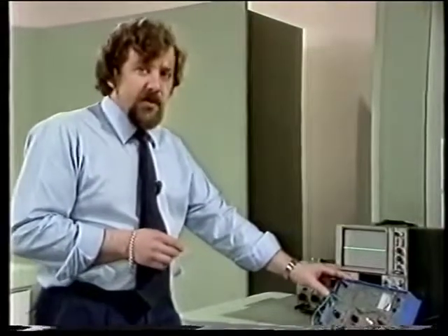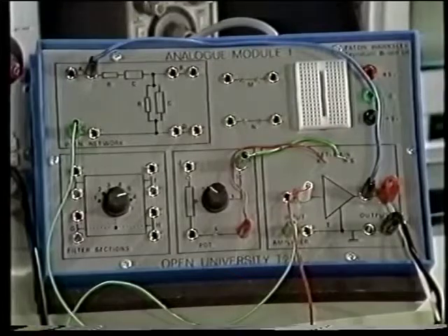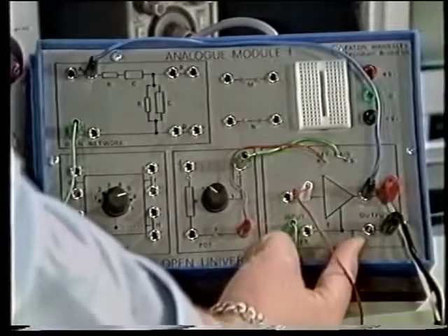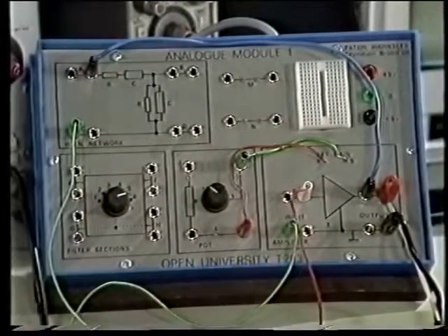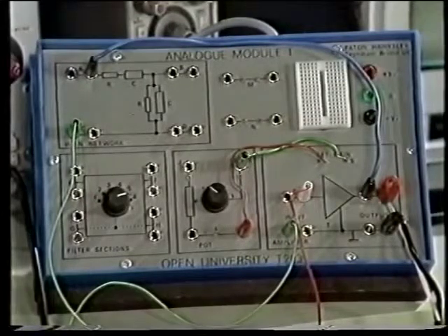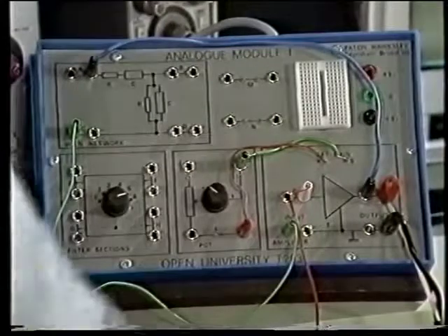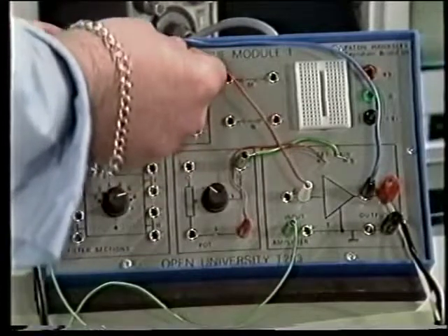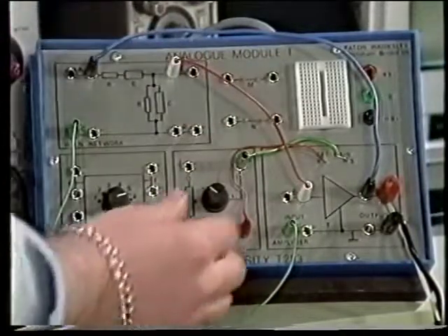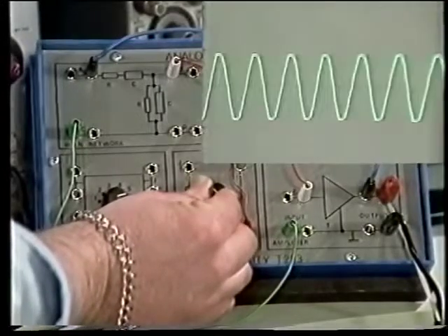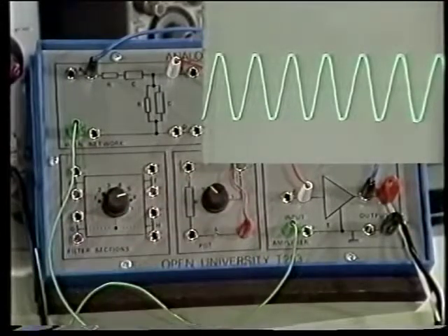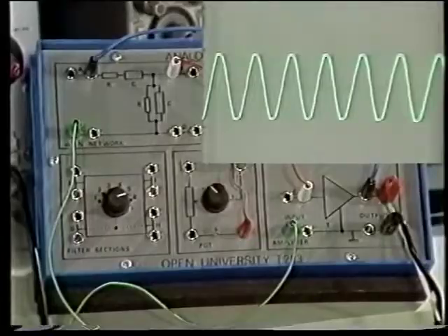As in the home experiment, I'm actually using one of the modules. I've nearly finished setting it up. This is the amplifier. Its output goes to the Wien network, and I can close the feedback loop going from the output of the amplifier to the input of the network. And if I get the gain right, you can see on the oscilloscope that it does indeed oscillate. I've measured this frequency, and it's about 700 Hertz.